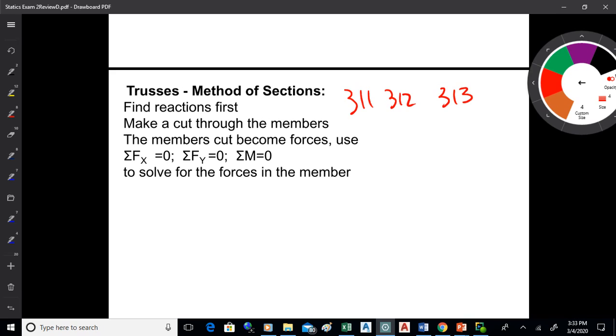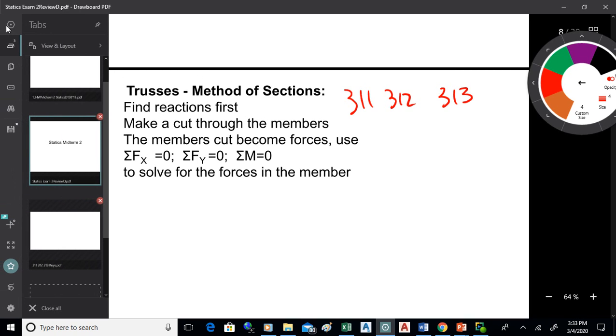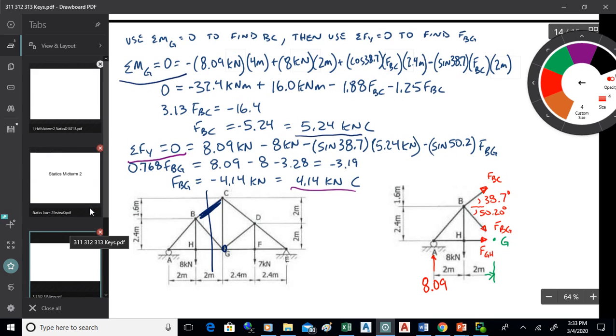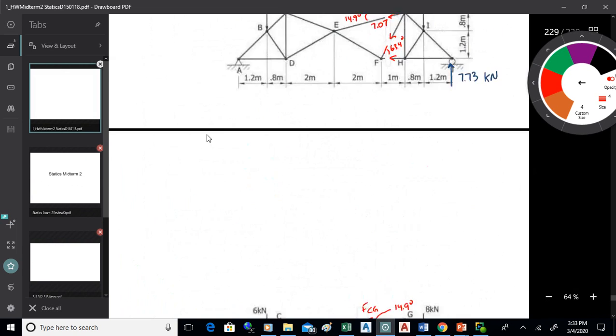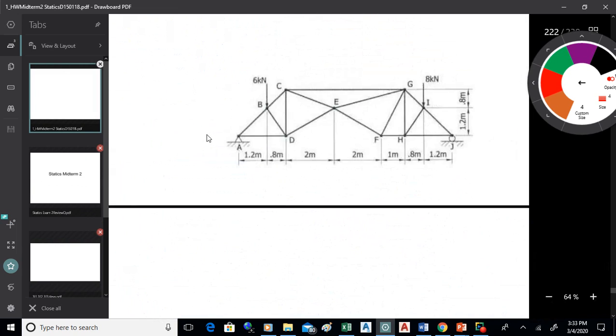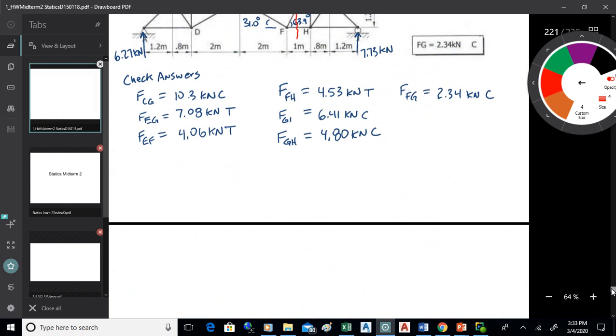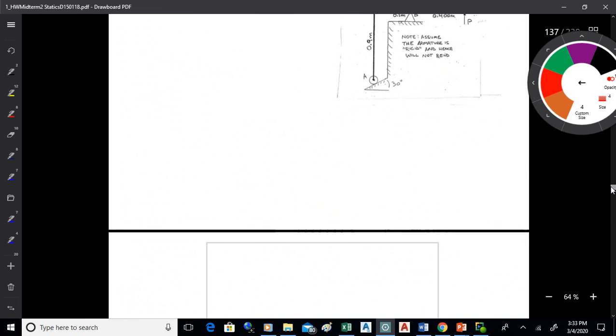Yeah, question there? On distributed loads, what's an example of a cut-up composite loading diagram? Cutting up a composite loading diagram on a distributed load. Oh, we've had a few of those. Let me think. Yeah, it's like a trapezoidal load typically. So when you take your triangle out of it and then you do your rectangle. Yeah, there's been a few of those, but you ask questions.